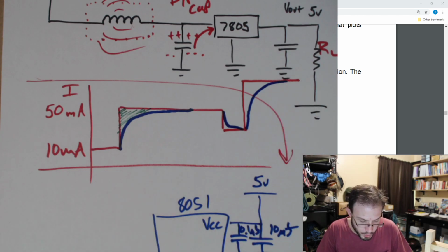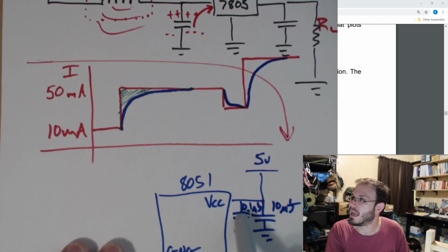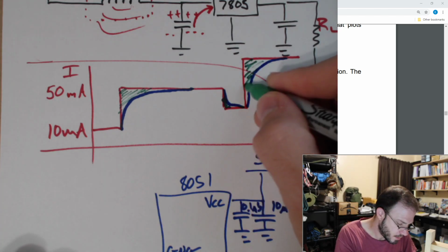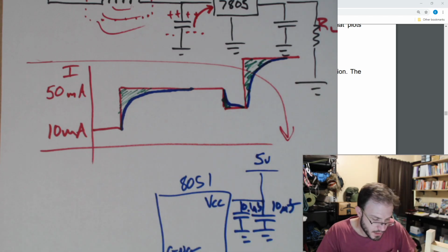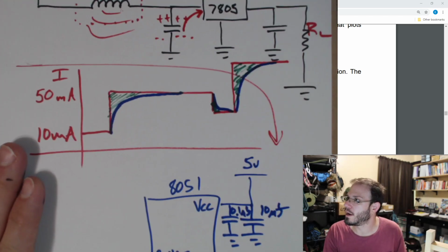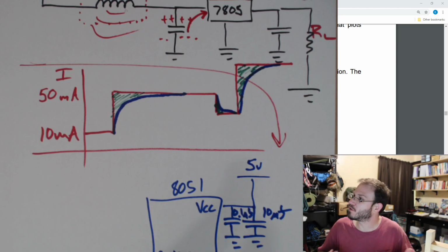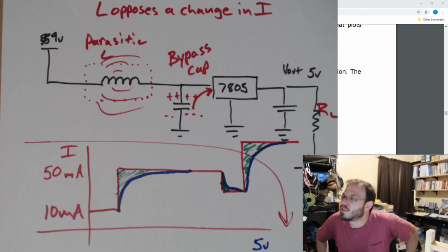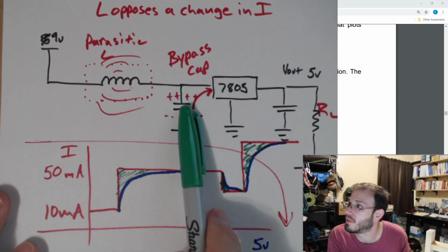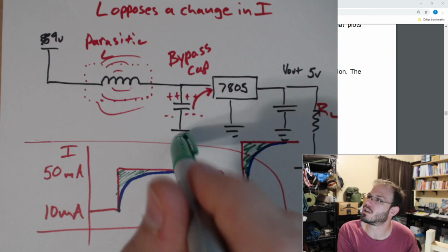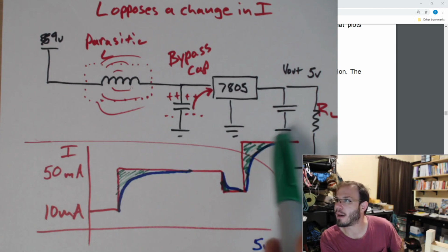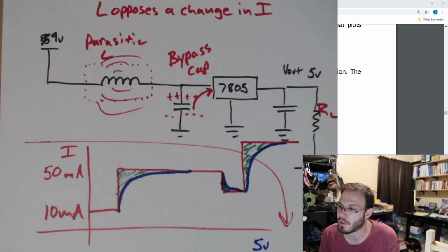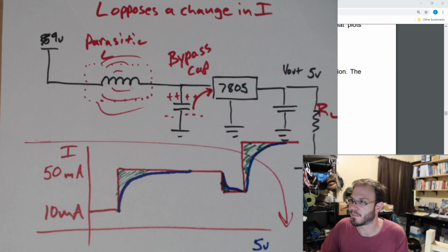And so the whole job of this bypass cap is to fill in those times when our device is having its mood swings due to this parasitic inductance, right? Okay, so that's the whole purpose for this first cap. That one I can at least do some explanation on. On this other cap, it's going to require a little more understanding of what's happening inside of the part. Does that kind of make sense?